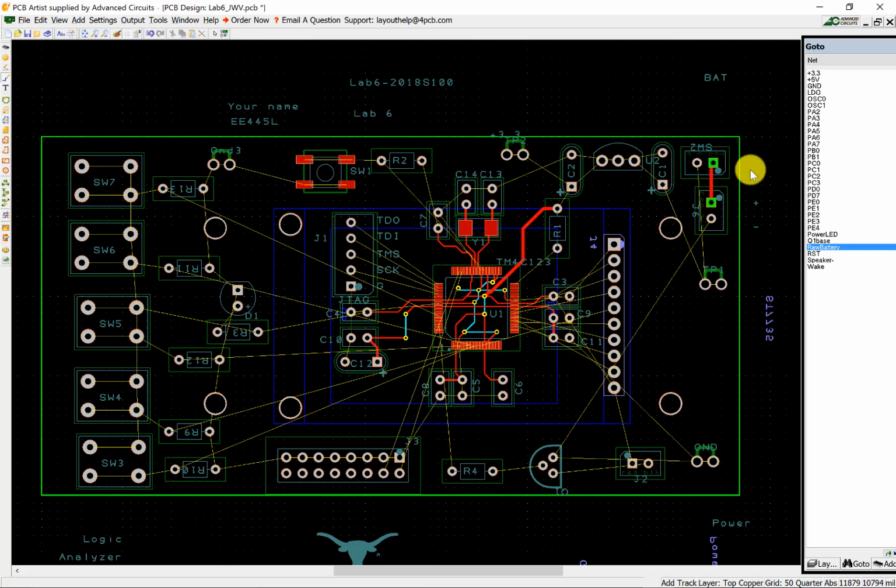All right, so I made a trace. And so electrically what's happening is the power's coming into this. This is going to be an external on-off switch, and that is going to be +5. And so if I move these things over, I can put my test point right in there.